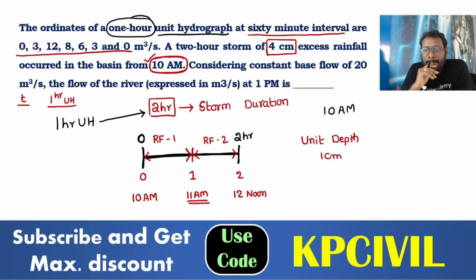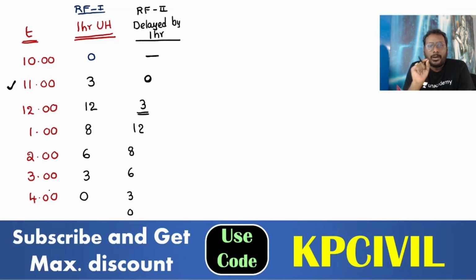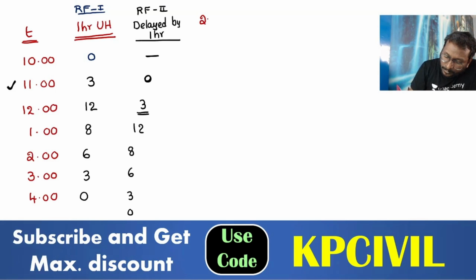What is our question? Considering constant base flow of 20, we need the flood discharge of the river at 1 p.m. Now you have the ordinates for rainfall 1 and ordinates for rainfall 2. Combined is 2 hour DRH only, no?